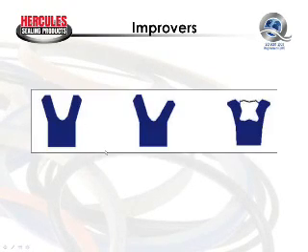And here we see our three types of U-seals again. Our symmetrical U-seal, which was basically the standard of the industry prior to the 60s. The introduction of the asymmetrical seal to reduce low pressure leakage on the static side of the seal, improve stability of the seal in the groove, and to give a better, more consistent contact surface between the dynamic sealing lip and the sealing surface. This was introduced in the 60s. Then we have the loaded U-seal, where the expander or energizer creates a greater radial force of the sealing lip against the sealing surface, giving us improved low-pressure sealability.